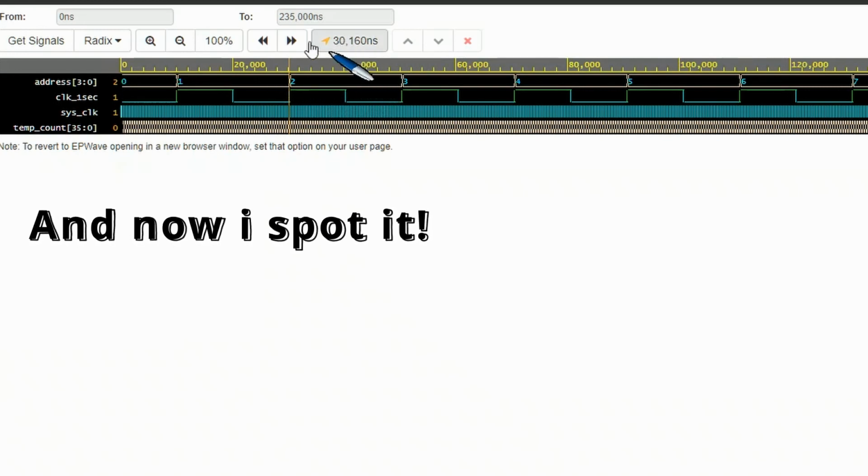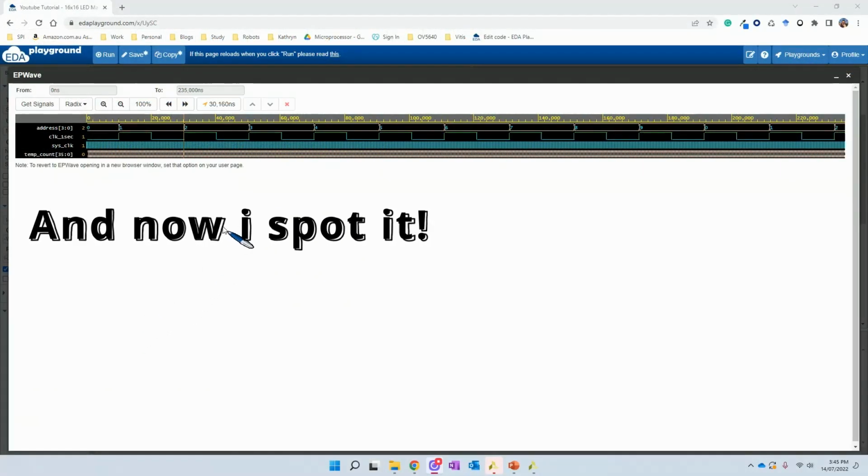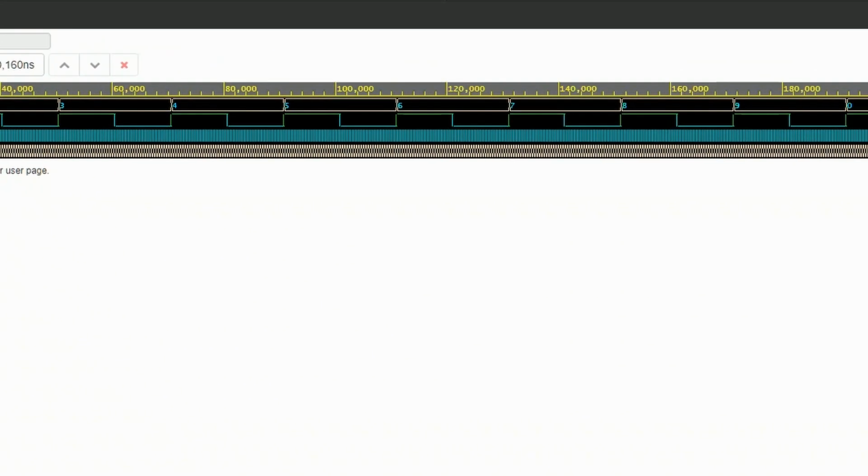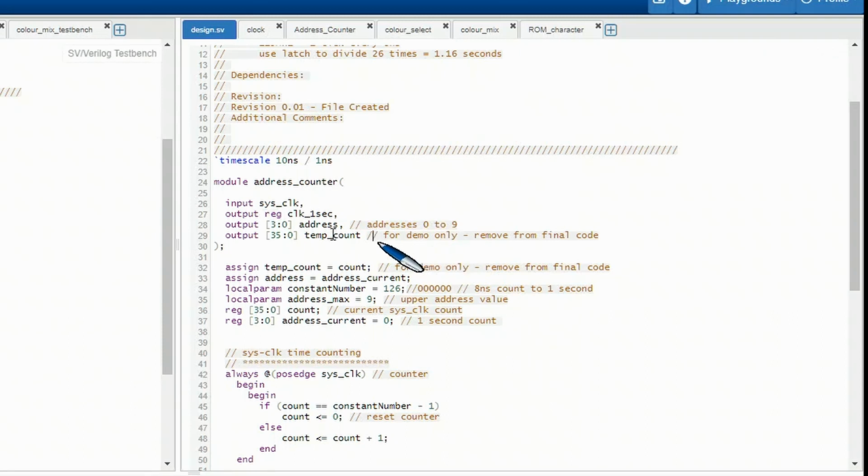Interestingly there. All right, so I've just noticed that I hadn't looked at my code well enough, and my 10 nanoseconds is occurring on the low going pulse instead of the next high, so we're going up slightly higher than what we want. Basically what that tells me is if I go back to my count, this value down here should be half. So if I halve that value, apart from that very first count, which would clean up after one cycle, it would be exact.